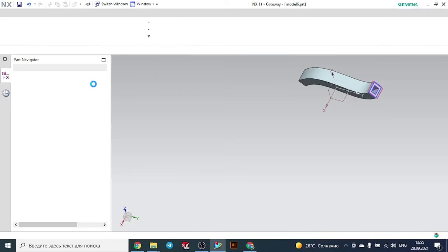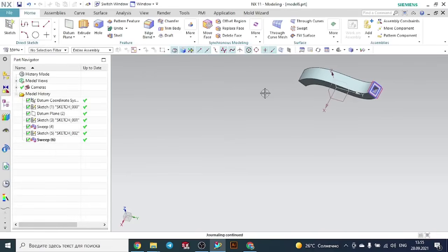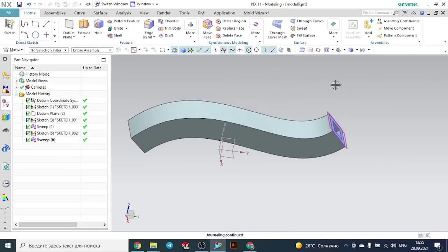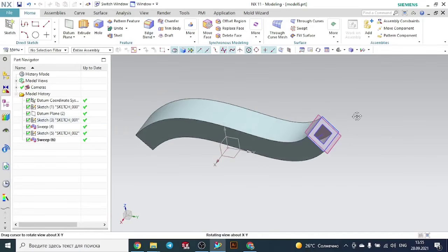So sweep along the guide. In this case, you need just one cross section, like here is the rectangle, and one path, meaning the guide curve. The cross section could be rectangular, triangular, circular, any shape could be. In this case, it's just a rectangle. So let's see with the rectangle. So open the new file,